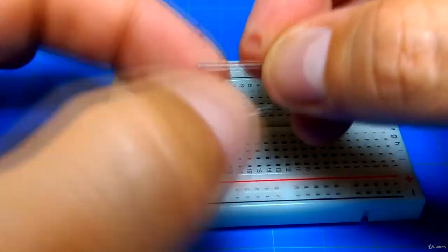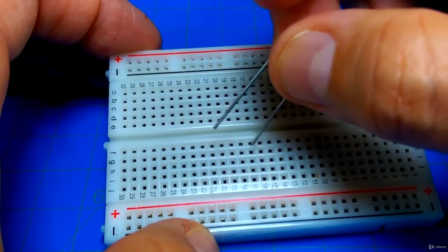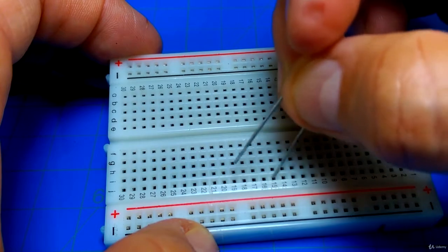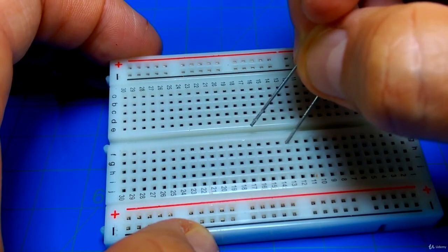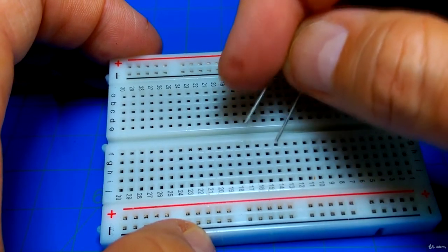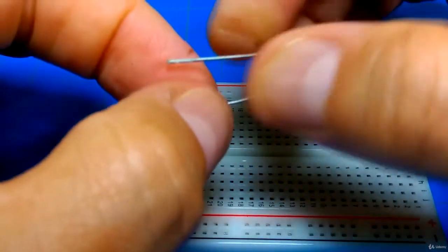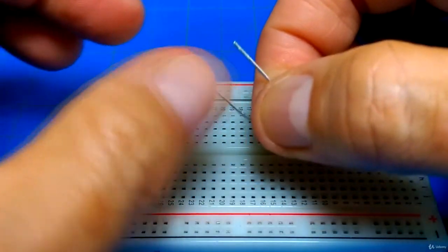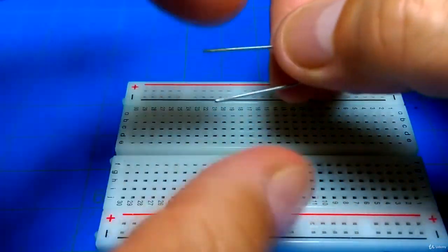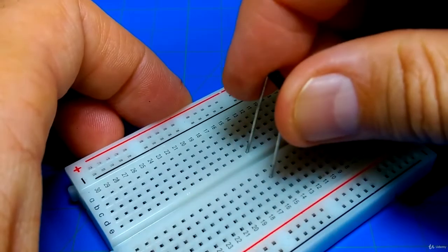Now, another thing you're going to notice, the ends are blunt, and they're going to make mechanical contact. There are little clips inside of here. So these wires are common like this. These clips allow current to flow in these columns. So if you put it here, this is all connected, right? If you look at these closely, they're little clips, and when you push something blunt in there, it's going to catch it. So what you typically do is take some sandpaper or a file and file these down a little bit, kind of chamfer them, and they'll go in a little bit better. So I'm going to put this one right in here.